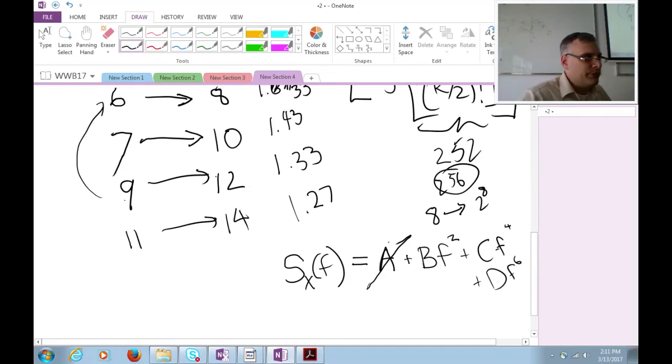However, you can play around with the codes, and it turns out that a subset of those balanced codes actually also get rid of this component. And a subset of those, for a very complicated code, will get rid of this component. So you can actually make very, very deep nulls by playing games with these balanced codes.